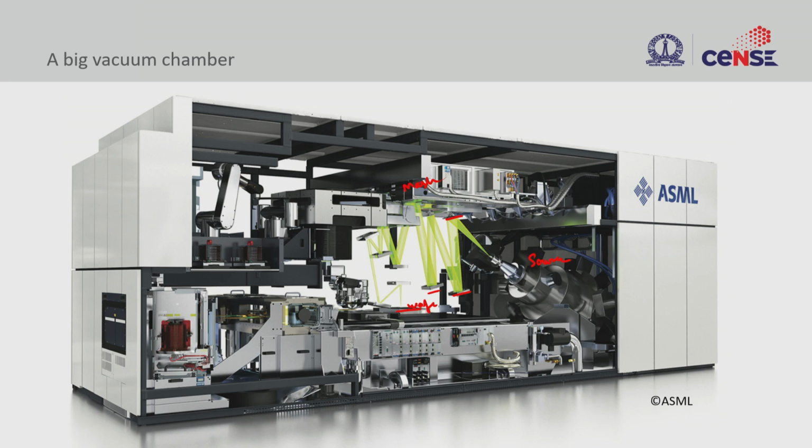Another interesting point here is that this whole chamber should be in vacuum. If you look at these lower wavelengths, the spectral efficiency of these sources is very low. So the amount of photons that you get is low, so you want to make it very efficient. In order to reduce dispersion of the photons, you should operate these optics inside a vacuum chamber, and that again is a very technically challenging task, where you have highly sophisticated reflective optics that need to be aligned.